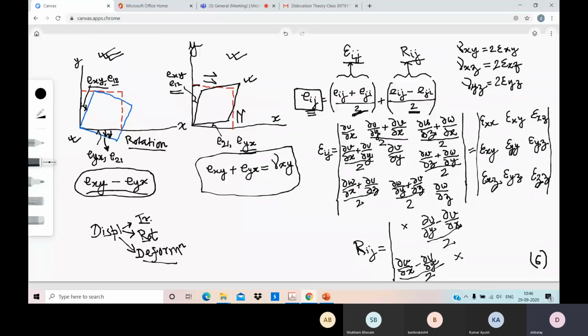So basically the relative displacement tensor I am dividing into two tensors, one tensor containing plus terms and one tensor containing minus terms. So see, the tensor containing plus terms, epsilon ij, now I am calling the strain tensor. So this particular tensor is my strain tensor. You can call it strain tensor because here the angular changes are represented by plus terms only.